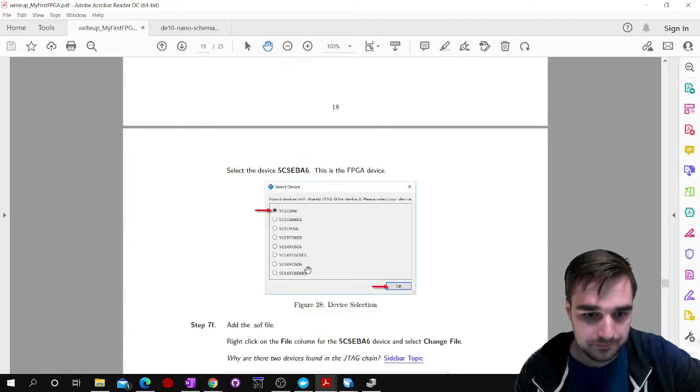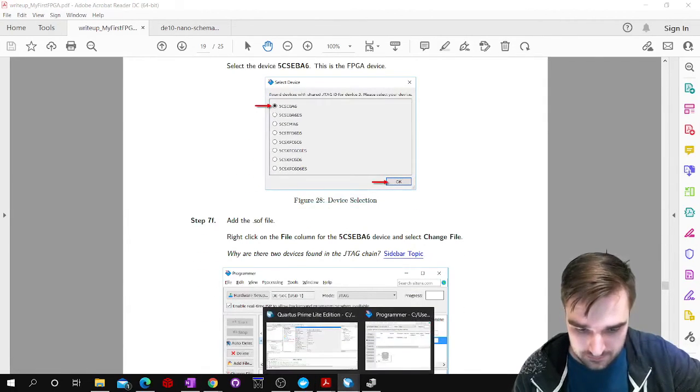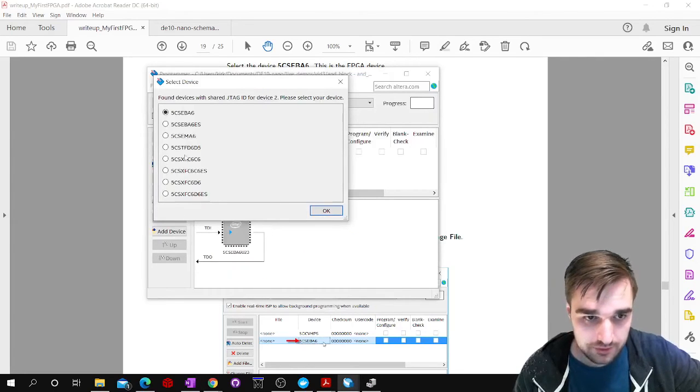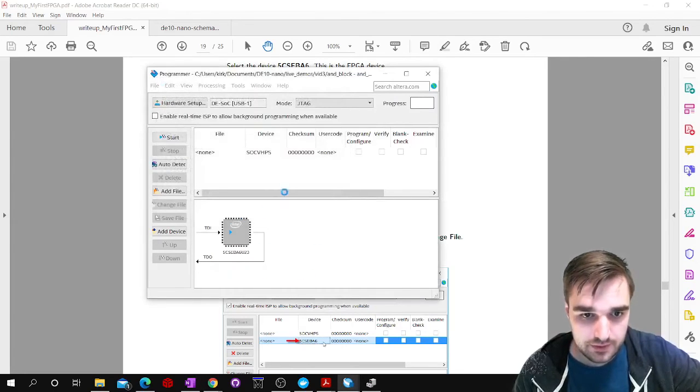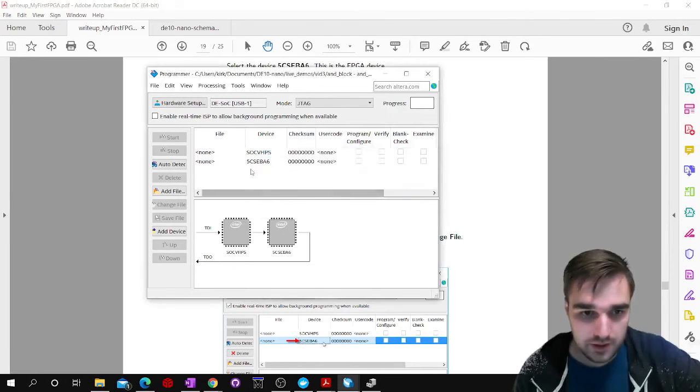We want the first one selected. Let's see, am I paused? No, we're good. We're rolling. Okay, good. Go back to the programmer. Yeah, first one selected, click OK. And say yes. Okay, and then this is our FPGA, the 5CSE-BA6.